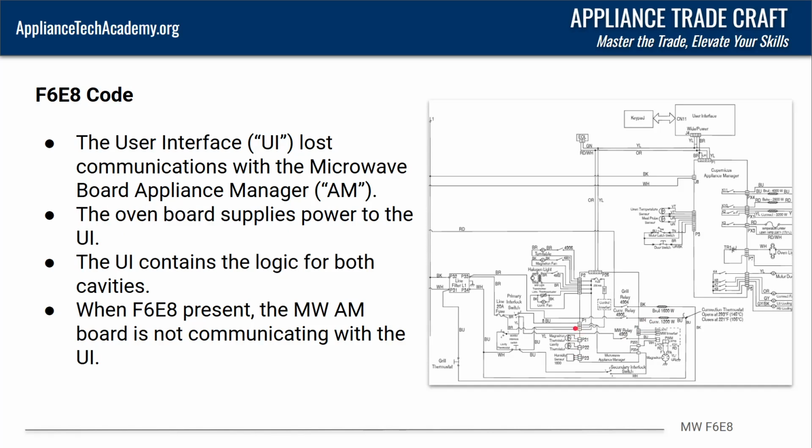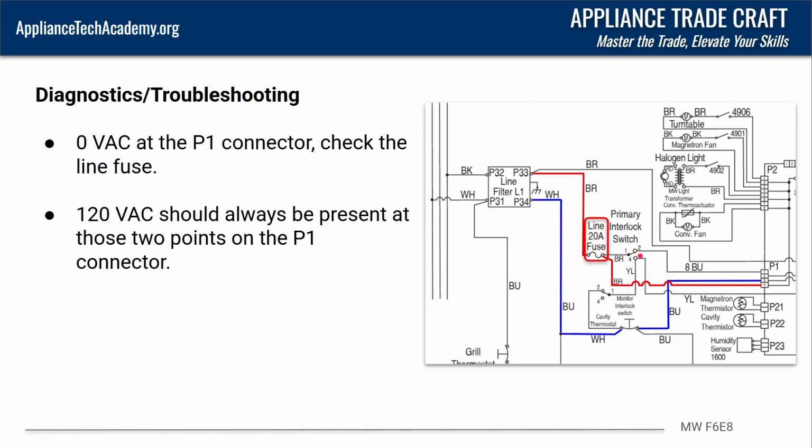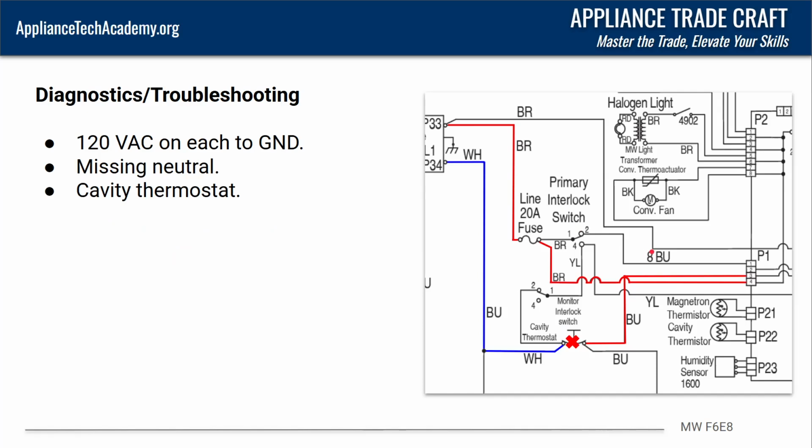You're checking from there to there, you see 0 volts. You think to yourself, okay, we're not getting any voltage. It's probably this fuse. You come check the fuse and guess what? It's good. It passes. Well, then what? If you have 0 volts when you're checking those two, and this is good, then guess what? This is where voltage potential really comes in handy, understanding this.